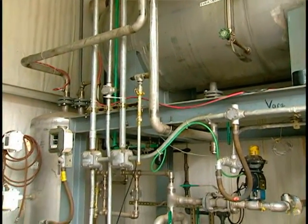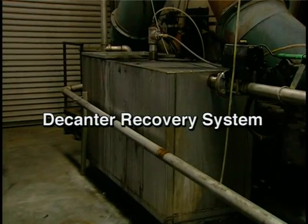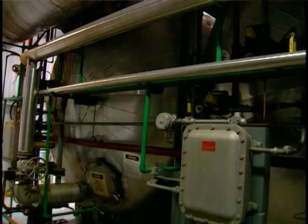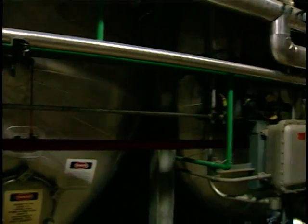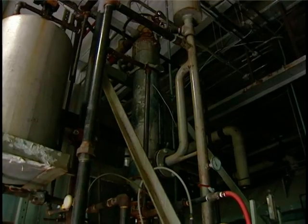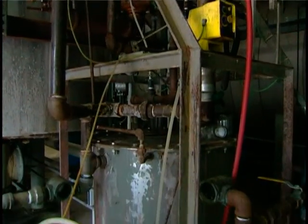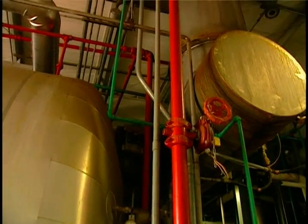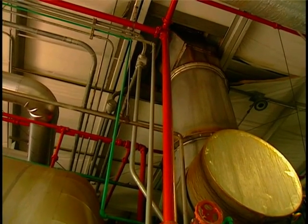If the quantity of organic vapor entering the adsorber is constant, a reduction in the amount recovered indicates reduced collection efficiency. If the quantity of recovered organic contaminant is monitored, a material balance can be used to evaluate the performance of the adsorber. With this approach, the quantity of organic material recovered over some time period is subtracted from the quantity of organic material used in the process during the same period to determine how much contaminant was lost to the atmosphere.